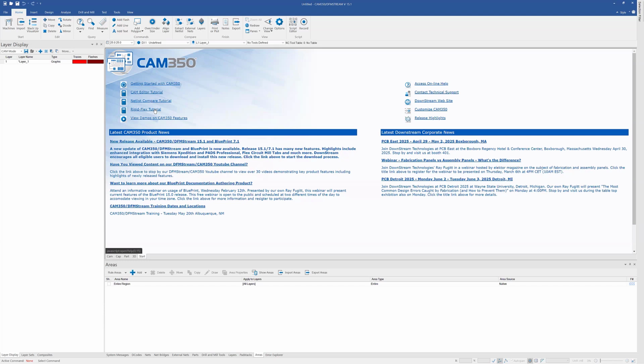All that information can be in the ODB++ or IPC 2581, but we're kind of locked into that Gerber and NC mentality, which really means we're asking the fabricators a lot. They basically are reverse engineering your design in order to get it built. So there's a lot more risk if you send Gerber and NC. So there is a tutorial on that intelligent format, and we do have a full set of analysis for Rigid Flex as well.